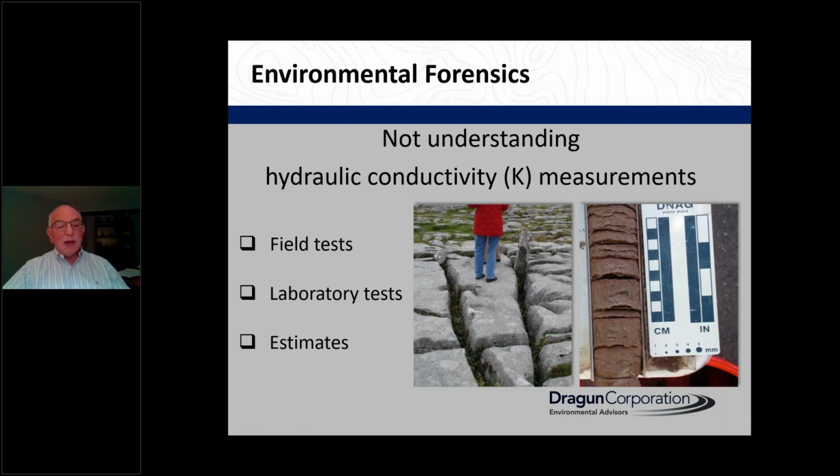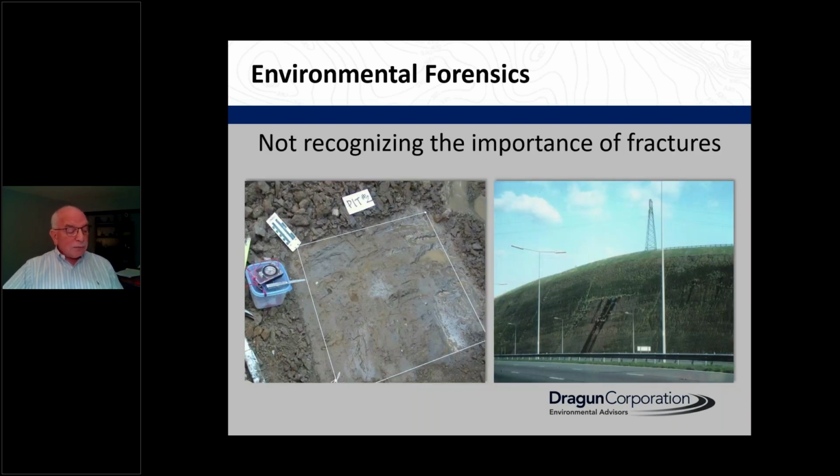Not recognizing the importance of fractures. We typically think of clay soils, like we see on the left, as being impermeable. We use clay soils for landfill liners. We use clay soils for sealing wells, but clay soils can have fractures, especially in the lower Great Lakes area.